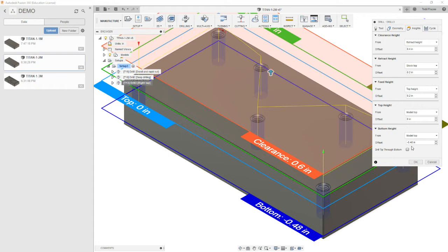So our print dimension says that we should have a threaded hole with 0.38 depth of thread minimum, fully formed. The first three teeth on the tap don't actually cut anything, or they cut progressively and don't form a full thread. So we're going to go about 100 thousandths, or 0.1 deeper, but that is still shallower than the 0.505 that our tap drill is going. Should leave enough room in the bottom for chip clearance and not break our tap.